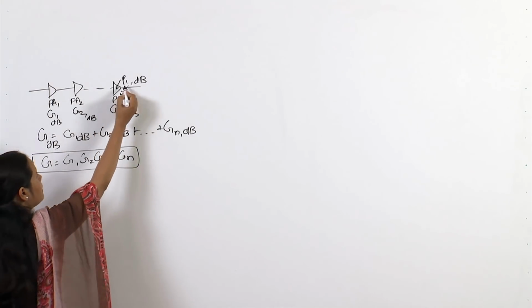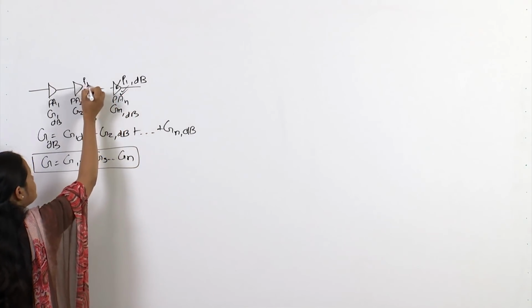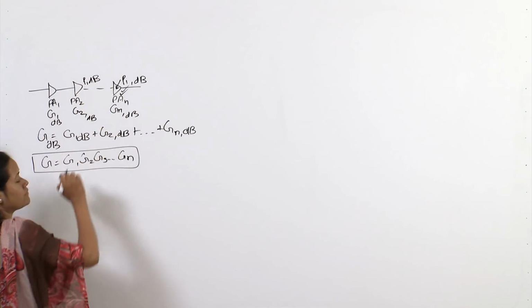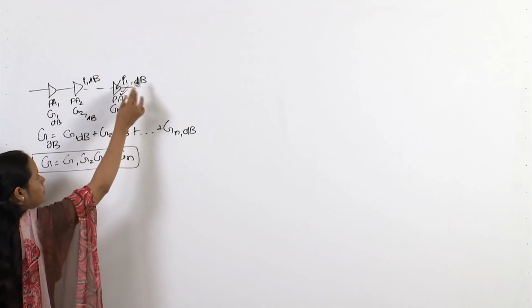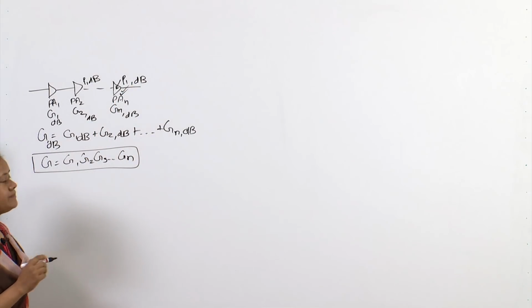So, we have to be careful about the P1 dB of each of the stages. At any stage the output power should not be beyond this P1 dB power.